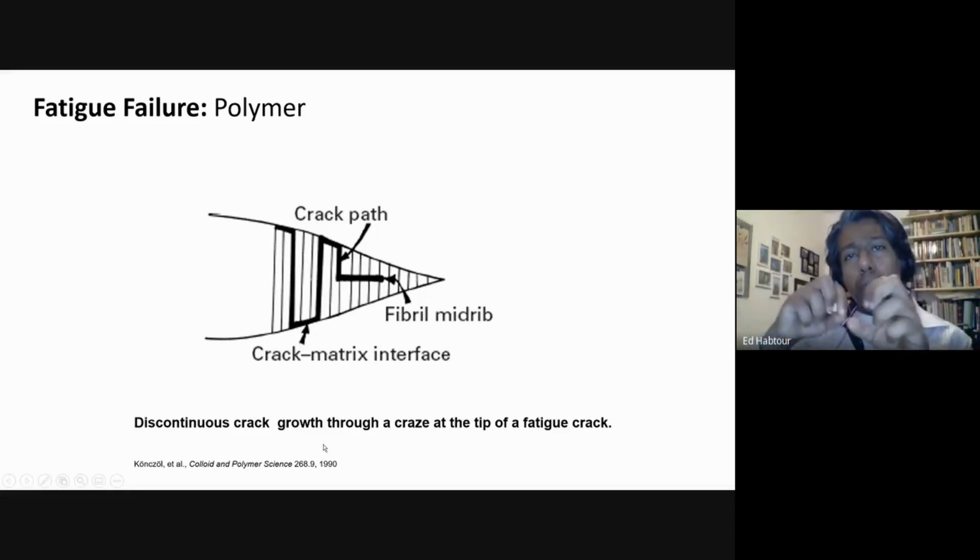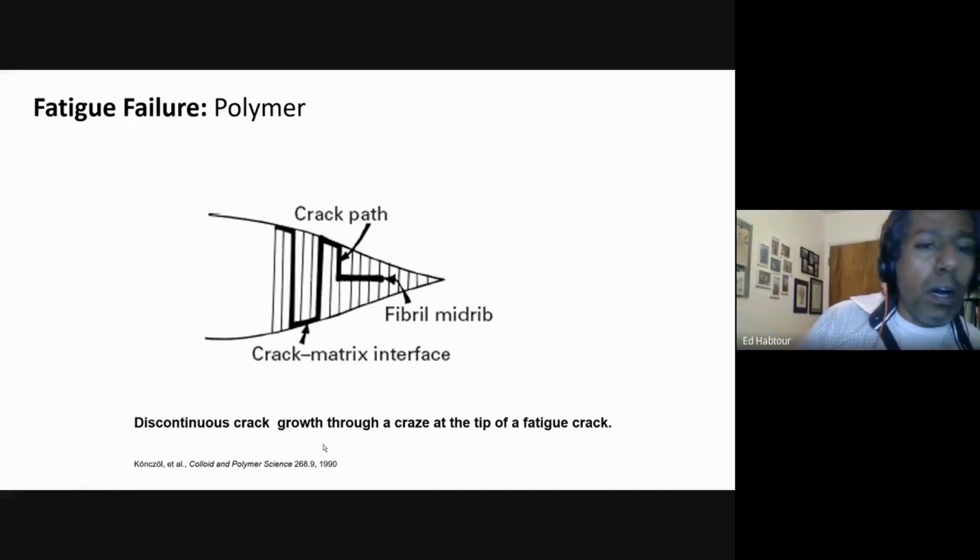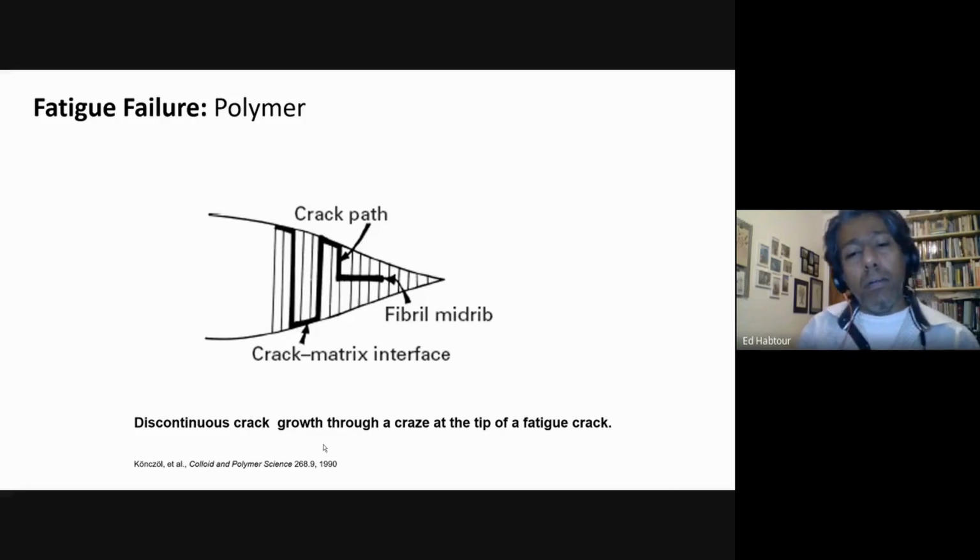I've showed you the incubation or the initiation, the wave propagation effect, and then the complete fracture or rupture. Here, it's more like a fibrous break in the material that looks almost like you're breaking a bunch of fibers. And you'll see that also, especially in composite materials, because they don't consist of grains, they consist of fibers. So you're breaking the matrix and then the individual fibers as the fatigue propagates.